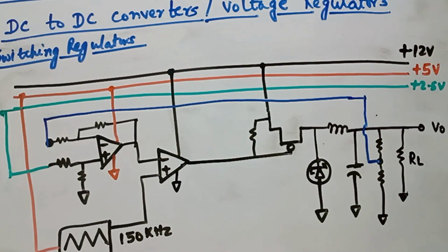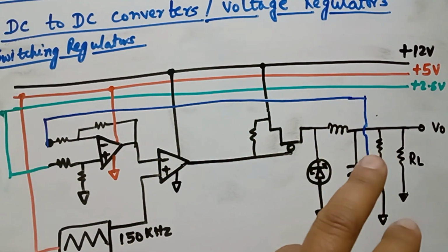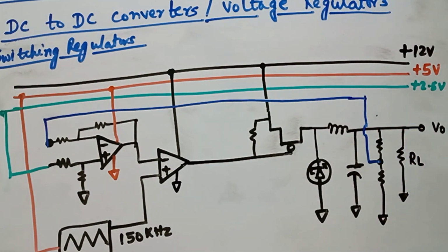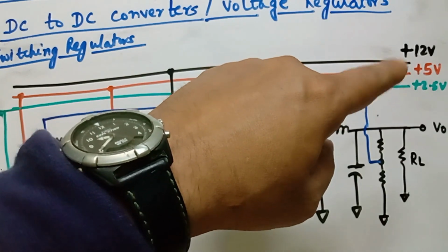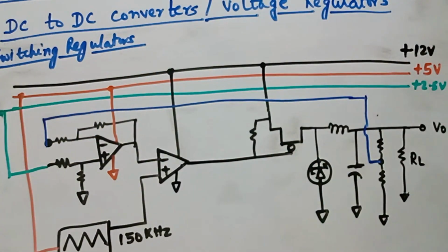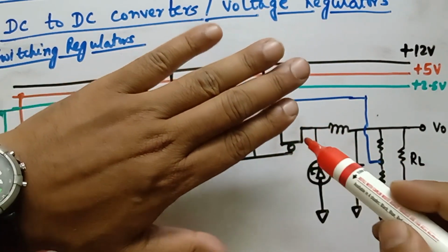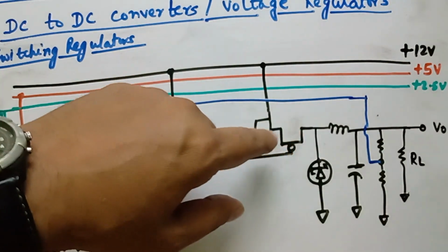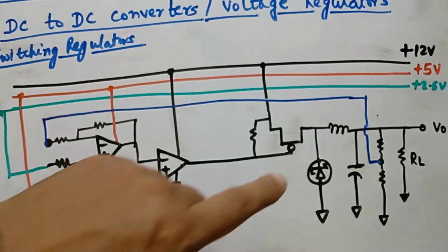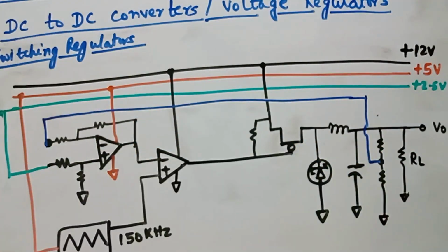So now here is the complete circuit diagram of a switching regulator's internals. The regulator inside generates a few voltages like 12 volt, 5 volt and 2.5 volt reference voltages. Since these are basically reference voltages and do not draw any current, these voltages do not vary and are almost a constant value. Now let me try mapping the components that we have been talking about so far. This part of the circuit is a switch. So that mechanical switch is now replaced by a PMOS, an electrical switch. And the Schottky diode, the inductance, capacitance, and the load resistance.